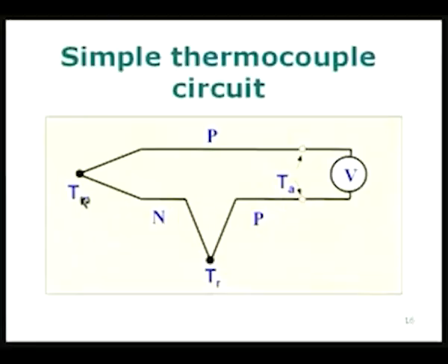Therefore, you can say that the Thomson effect, of course, the Peltier effect is localized at the junction. In view of the fact that these wires are very long and the temperature variation is localized near the junctions, we can say that the thermoelectric phenomena which is taking place is localized to the junction area, and therefore, we need not waste the good material, P material or N material, by having very long wires made up of thermocouple wires.